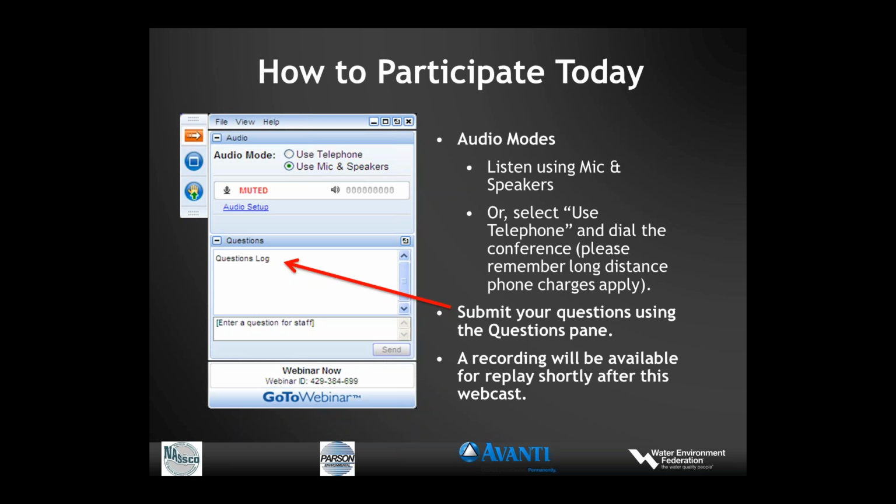Okay. Another question was, in reviewing references, is there a rule of thumb for what ranges of pipe sizes are considered similar? For example, installing 18-inch CIPP, is that significantly different than 24-inch or 36-inch? That's a good question. I would say 8-inch through 12-inch, pretty similar, maybe on up to 15-inch.